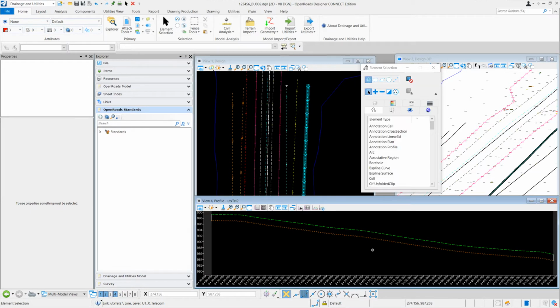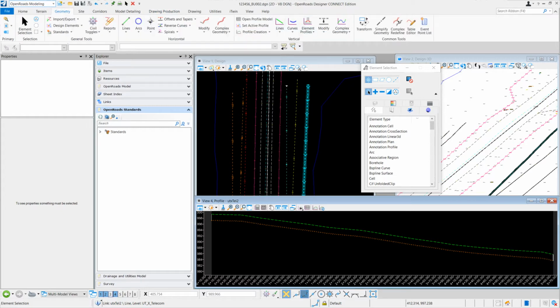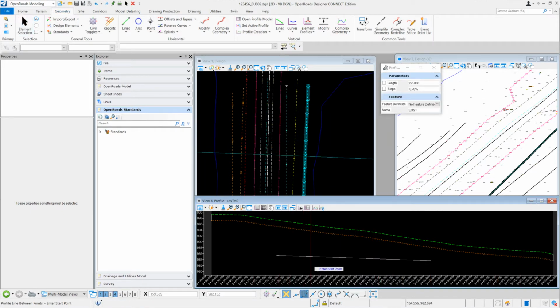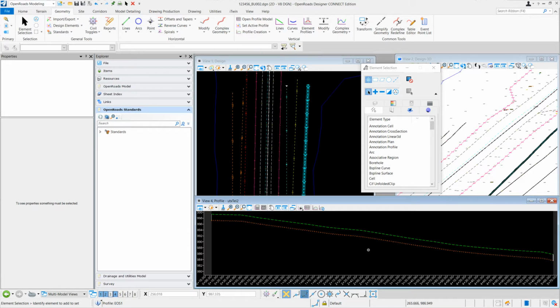It's complicated. You can draw in your own profile all you want. You can use all of these tools over in the geometry, the vertical section, to draw in your own stuff and just make that the new active one. Nothing's stopping you from just saying, hey, you know what, this is my profile, right? Once you make that active, you will see that it will get the right symbology. So as you're drawing this, the feature definition doesn't really matter, because when you make it active, you'll see it'll get set.